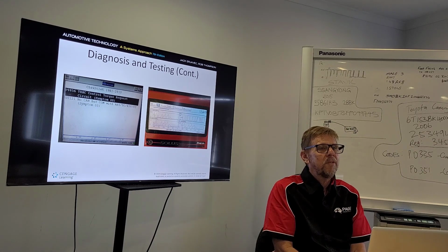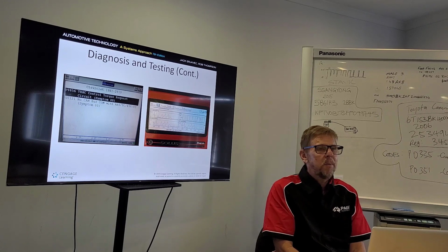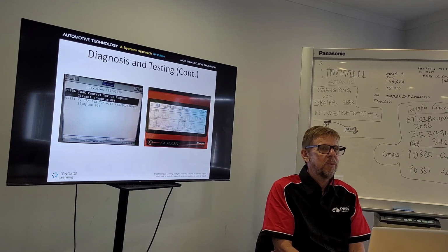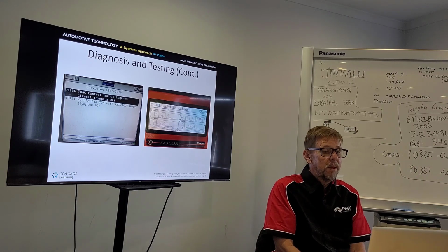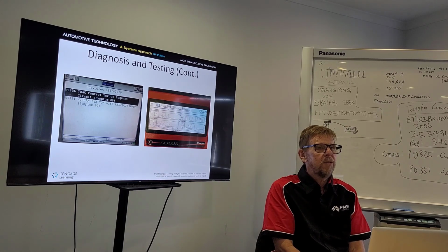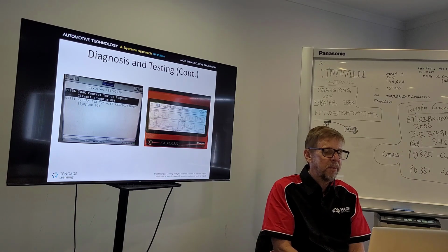No. What happens if we do a full scan of the vehicle? We probably should have done that at the beginning, of course, but we would soon see if there was a module that was not on the CAN bus, wouldn't we? So that's one way. But if it's an intermittent problem or a corrupted signal, we'd probably use our oscilloscope and check the wave pattern and have a look at it that way. All right.